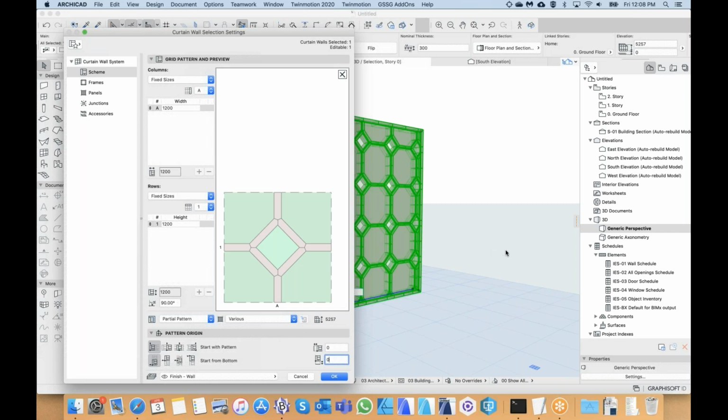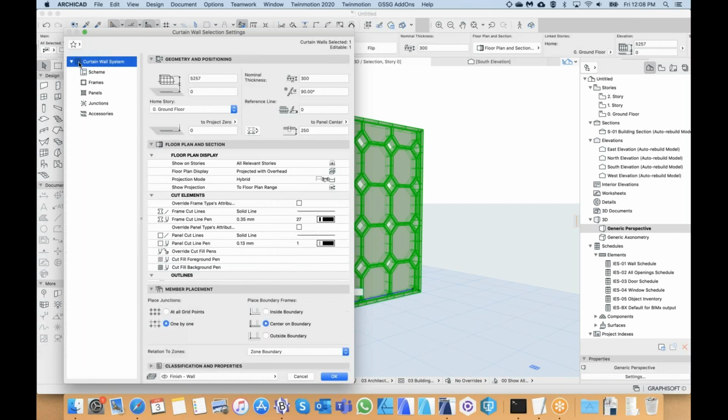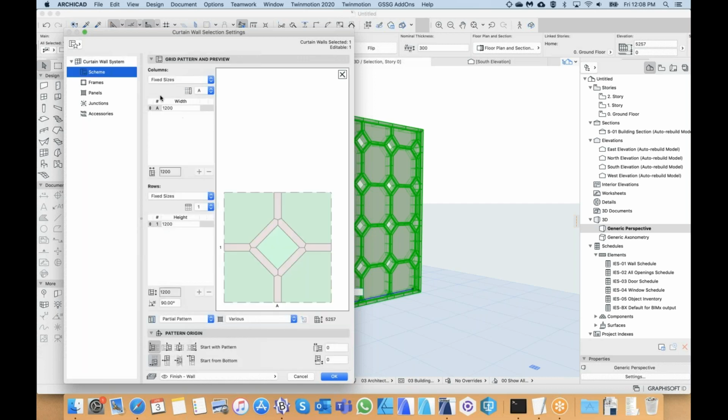When I stretch up, the diamond doesn't extend up. Gary, in your settings, you see the diamond shape as the scheme. Yes. Then just choose your curtain wall system and then just increase the height in the settings. A, B, C, okay. So we should only have an A and a 1 because we technically can't add more. So Jessica, do you see your diamond shape in here?